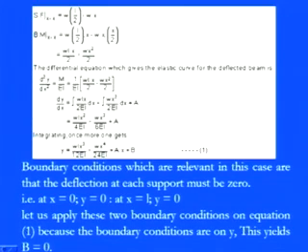Again by integrating we have the deflection equation which carries two different constants, and one can easily get those constants by putting in the boundary conditions. So by integrating the slope equation again, we have the deflection y for a simply supported beam carrying a UDL of intensity W. The deflection y is equal to WLx³ by 12EI, because by integrating, x² by 4 becomes x³ by 3, and since 4 is already in the denominator, we have WLx³ by 12EI, minus Wx⁴ by 24EI, plus Ax plus B.